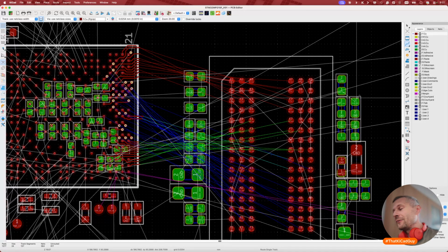But if you need to route the most difficult to route path, you need to know your constraints. And the constraints are, of course, all the vias for the other things, all the tracks for the other things, because you can't prioritize one factor of the design and omit all the others.